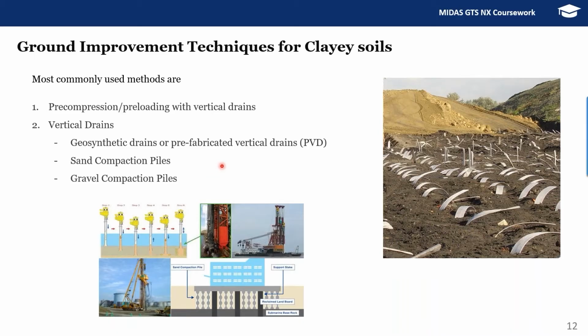In this session, we are not going to model the vertical drains, but we are going to simulate the behavior of the vertical drains in the software. We can even model them, but in this session we'll be simulating them, and we'll see how this simulation leads to the dissipation of pore water pressure and thereby an increase in the settlement.